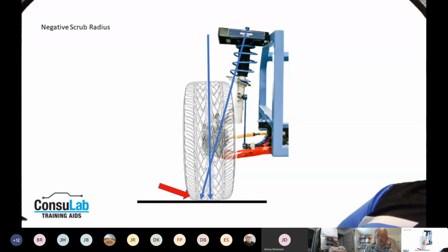But there are systems out there where we adjust the front camber at the middle point, where the knuckle meets the strut. And in that case, we're actually changing the included angle and having less effect on SAI. So we always have to be cautious of that. And there are some reasons why manufacturers don't build any adjustment in there: they don't want you changing the included angle. They want you to figure out what's wrong and fix it. Okay.